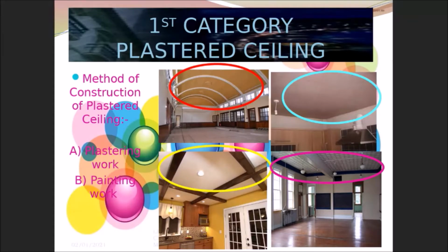I always mention this in our discussion so that you know if the work has curvature, either for the ceiling or for the length on plan, you have to measure separately as per 1.5.